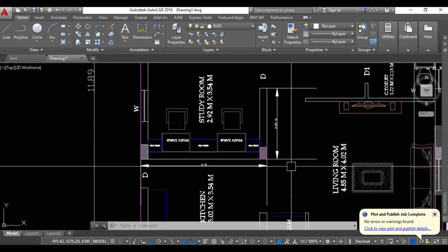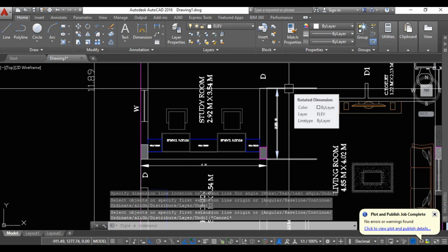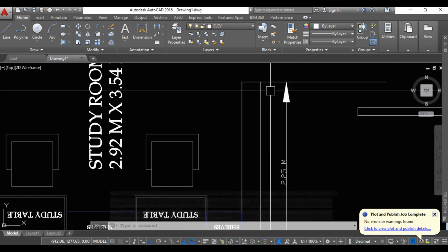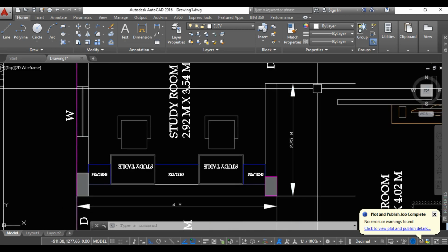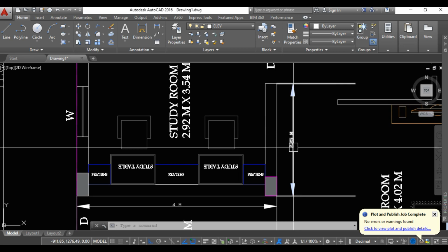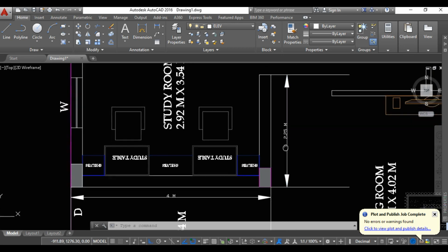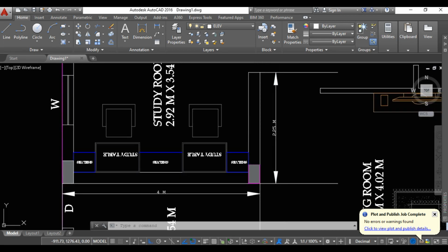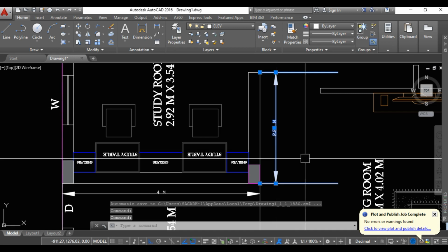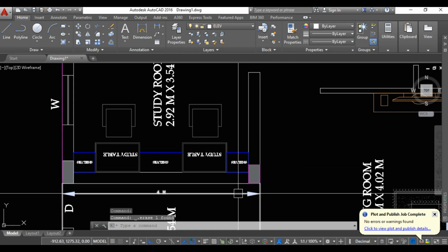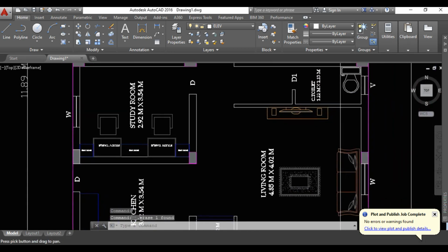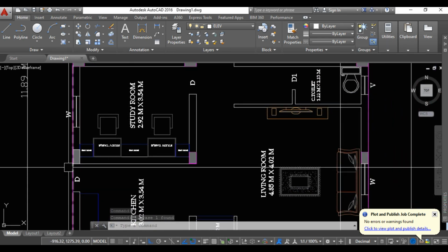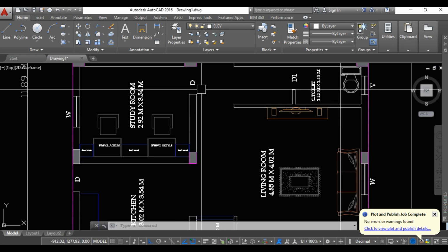If you want to remove these extension lines, you go to the dimension style and you can remove them. I have described this very clearly there, about the extension line and the dimension we are showing. If you want to change this font style also, all these things we can do in your dimension style editor. It is already discussed in dimension style, but I have not discussed DIM. So this DIM is going to work for the continuation of your work. If you want to take the dimension of this line, no need to press space, or to write once again the command key DLI or D angular.